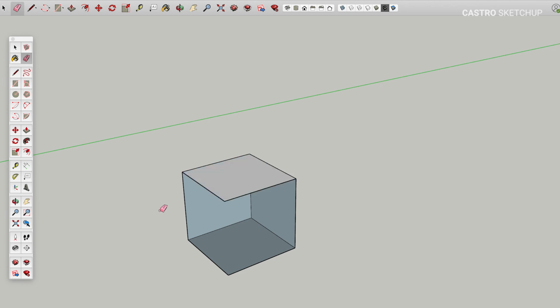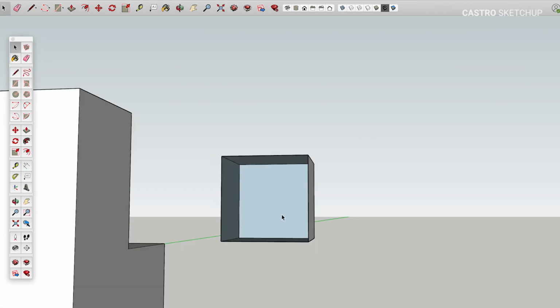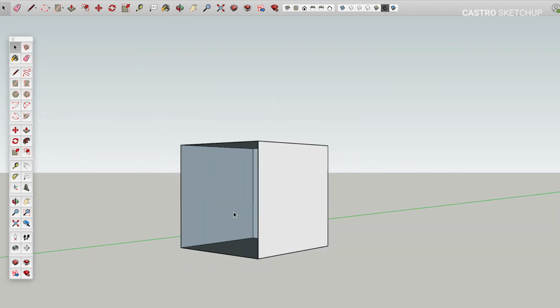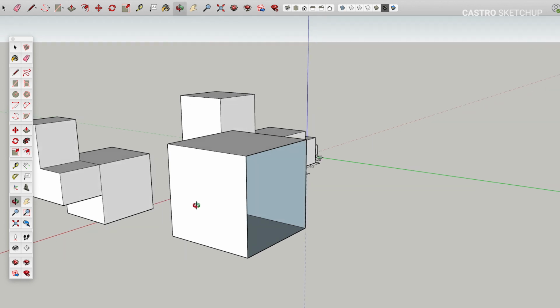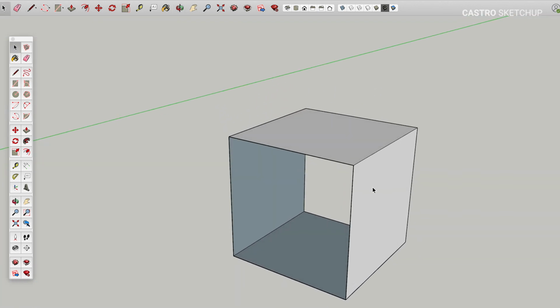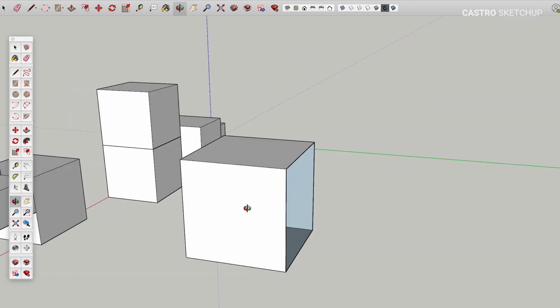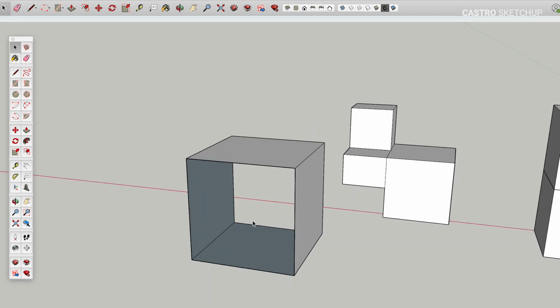So for those reasons, because it is very easy to delete lines and the geometry that goes with it, I highly advise that you use the selection and the delete command from the keyboard to delete any geometry or items that are unnecessary that you no longer want. Because if you do it the other way, there's a high risk of you deleting a geometry that could affect another surface without you seeing it right away, and then noticing down the line that that was a mistake.